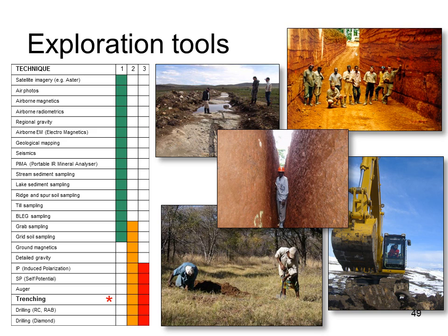Trenching provides a link between the indirect geochemical or geophysical methods and direct soil drill sampling. It's cheap, it's quick, and it provides valuable information on rock type, structure, mineralogy, and grade. It's used on a wide variety of deposit types. Environmental regulations usually require that the trenches are filled in and revegetated after mapping and sampling are complete.